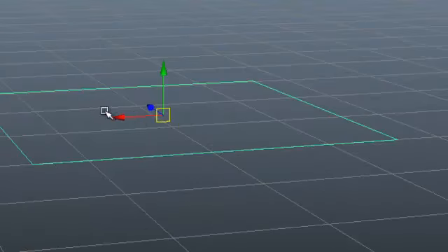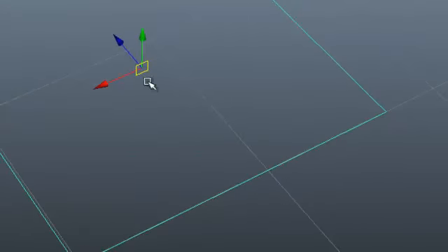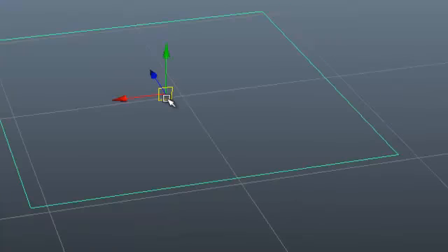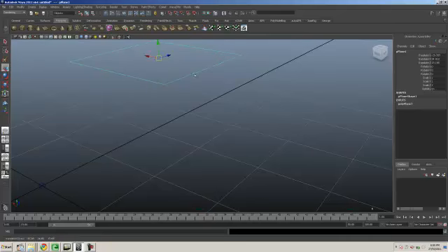I can click right over here, nothing, to turn it back on. I do the same thing. Keeping my Control button pressed, I left click on the center, and there you go. You see that square is back on. That means I can move it in any direction right now in my camera axis. But if I turn off my Y axis and move it here, it's not going to go up, but it's going to move in this plane right there, the X and Y plane.